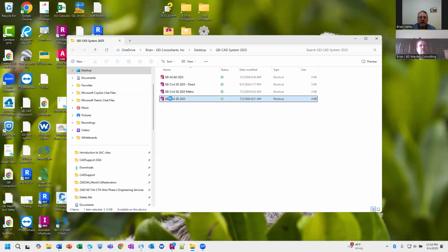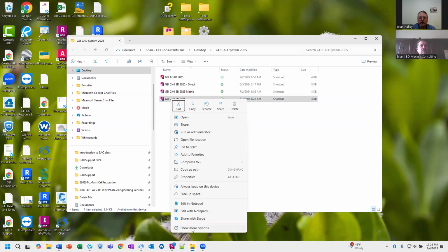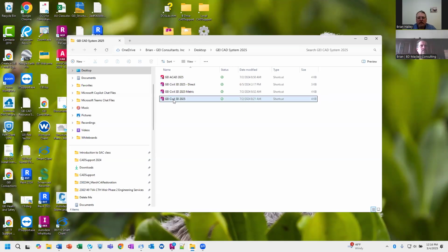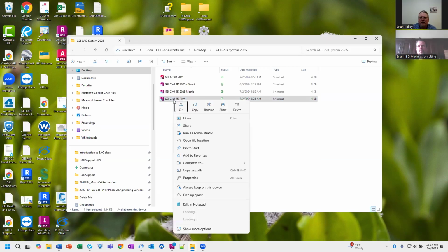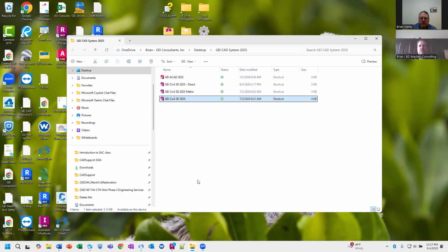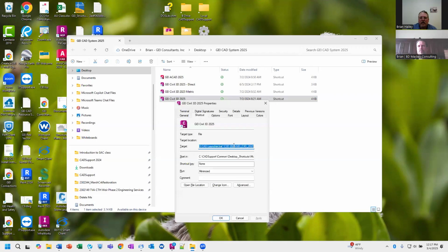All right, so I have a shortcut here, and this is not going to Civil 3D. We actually hired an Autodesk reseller to set this up for us. They had a custom little program, but you can just do this with a basic RoboCopy. What you would do in the properties is set this to run a BAT file that runs a RoboCopy that syncs the network files to the local drive if it can find that network drive, and then launch the program. So that's the way we do it here.